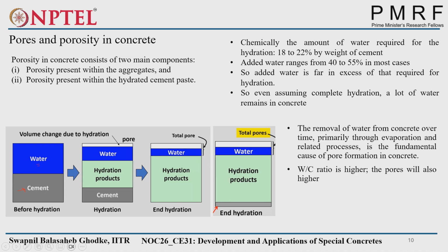So this indicates the removal of water from concrete over time, primarily through evaporation and related processes. It is the fundamental cause of pore formation in concrete. And if the pores are interconnected, that will be responsible for the permeability. We saw that in the first week lecture also. Last question is about interconnected pores and dispersed pores, which will affect the permeability more.